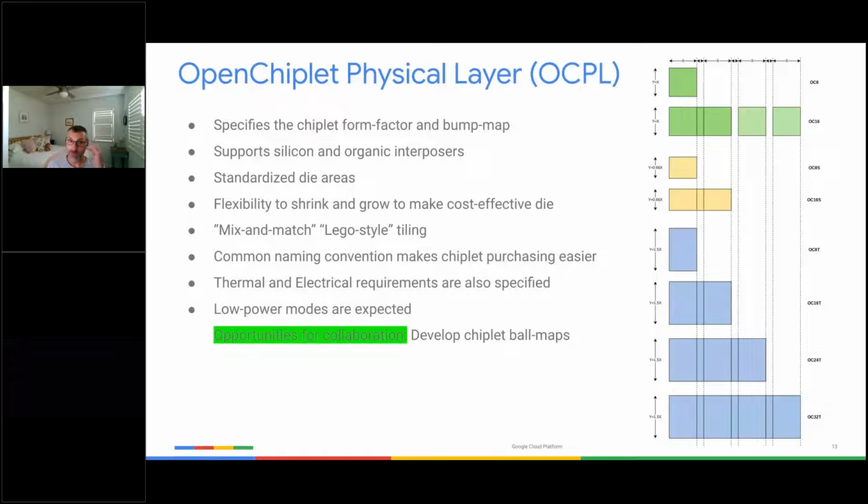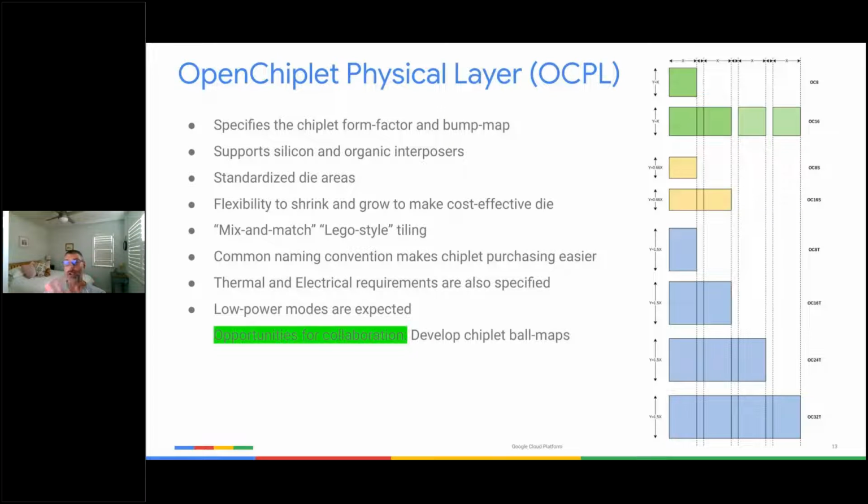So Ben, is there an expectation in the specification where the chiplet vendors would provide the full production defect type test, the DFT test, for each chiplet? Yeah, I see what you mean. Obviously the chiplets are being supplied in a known good die model, so the bare die that the OSAT is receiving have been through a KGD style test.